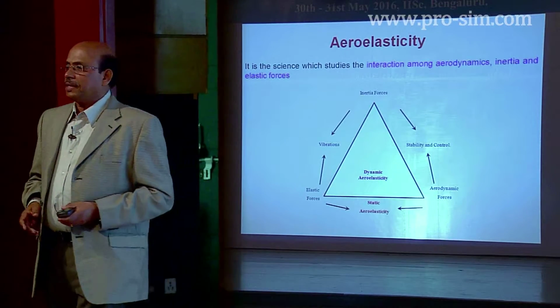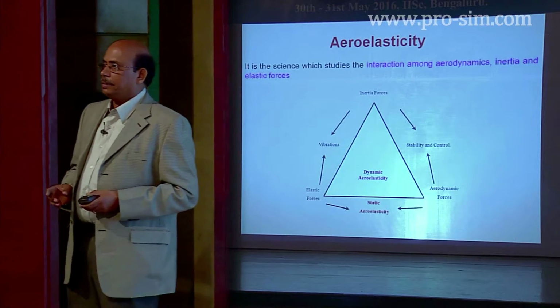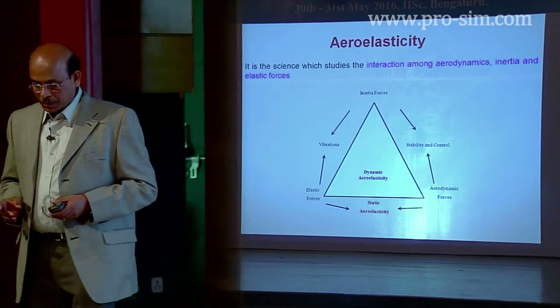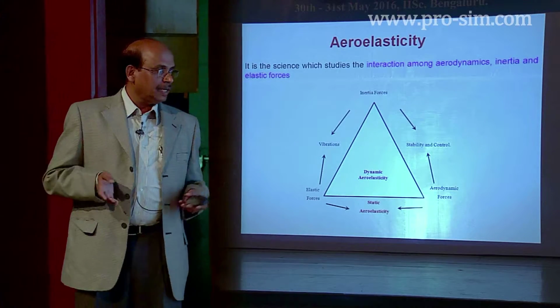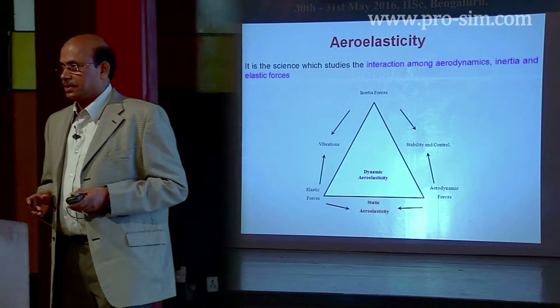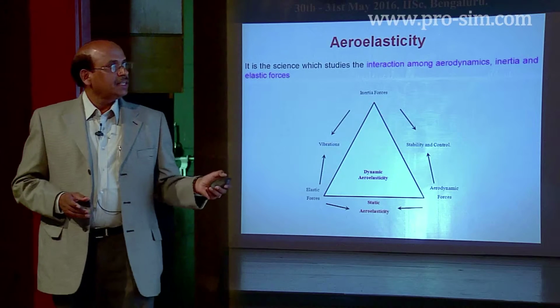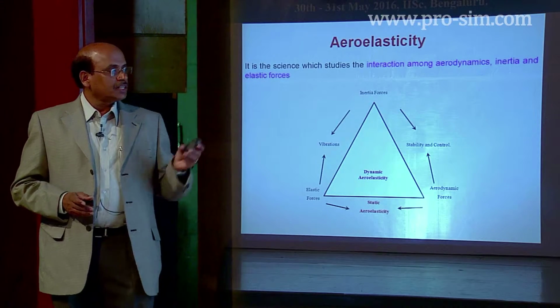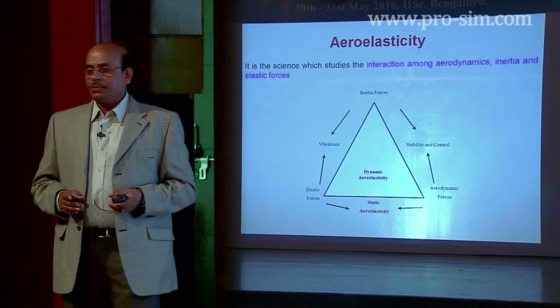Coming to the topic of aeroelasticity, because most of you are introduced to dynamics by now. Basically we have inertial forces, elastic forces and aerodynamic forces which come into the picture when we are dealing with aircraft structures. If we consider the interaction between the inertial forces and the elastic forces, that leads to what are known as the regular vibration problems.